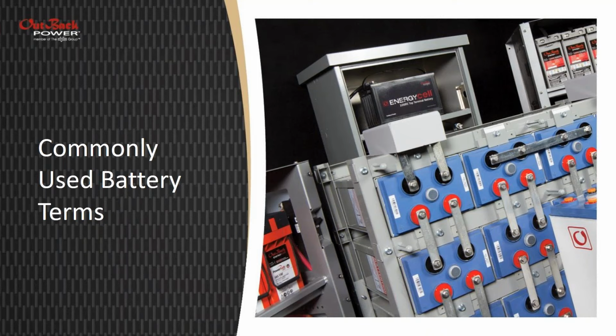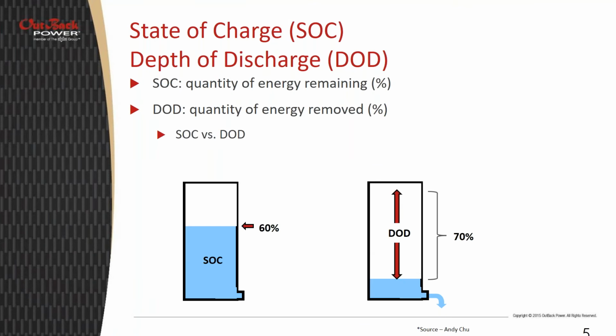Okay, so commonly used battery terms. State of charge and depth of discharge. These two names can really be interchanged. It's mostly, are you a glass half full kind of person, or a glass half empty kind of person? State of charge, as we define it, is the quantity of energy remaining in that battery as a percentage. As you can see on the left, we have our tank of water that we're going to assume is similar to energy stored in a battery, and it's at a 60% state of charge. So there's 60% of that water left.